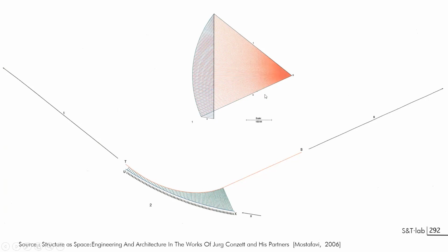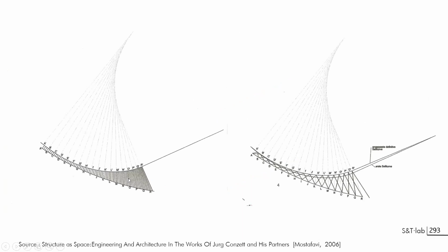So these are the forces in the hanging line, and these are the forces in the successive segments of the lower funicular. Working on this, there will be a graphical construction to define the ideal direction of each of these suspended forces. And you can also see that by using skew or diagonal hangers for each of these loads here, we put additional tension forces on the several funiculars that will help to stabilize the system and enhance the quality of the equilibrium.